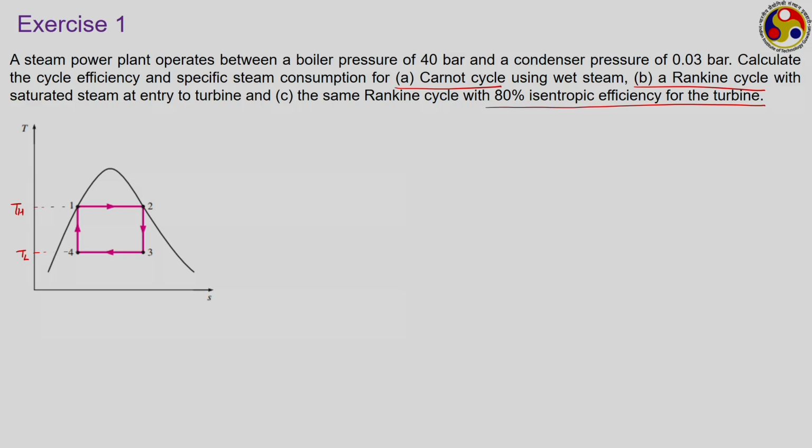And so, the temperature TH, which in this case is equal to T1 and T2, should be equal to T sat corresponding to this boiler pressure, which is 40 bar. I have used the data table which we have used earlier also. From the table we are writing this to be equal to 250.35 degrees Celsius, and if required we can convert to absolute temperature also, 523.5 Kelvin.